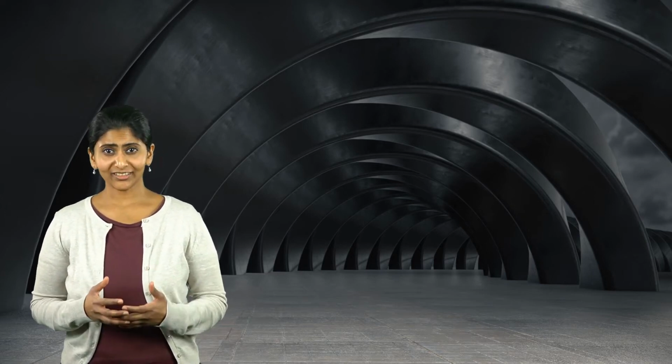In this section, we learn about the different ways in which bolts are connected to the rest of the assembly. When bolts are represented as line bodies, we often use beam connections, and when bolts are modeled as solid bodies, we use contact connections to define the interaction between the bolts and the mating parts.